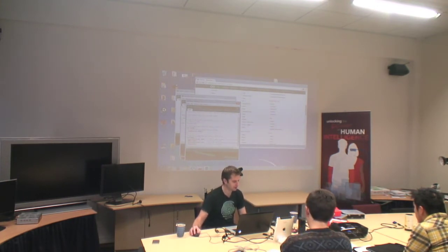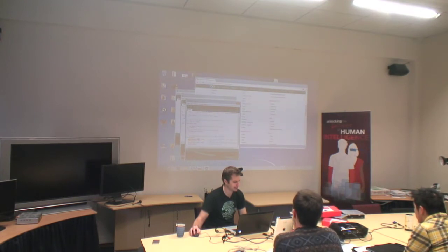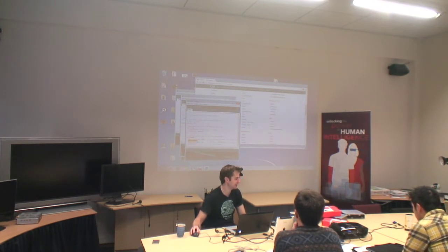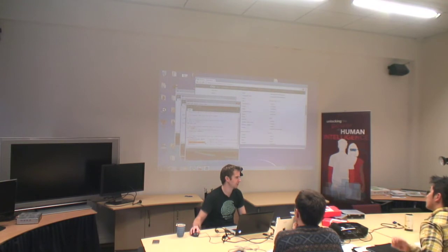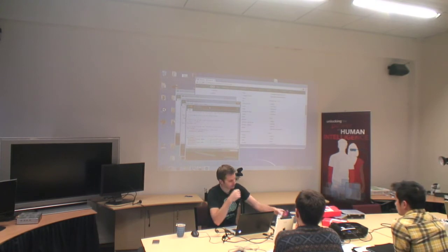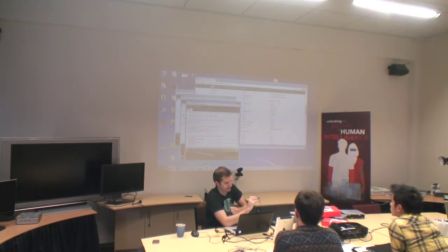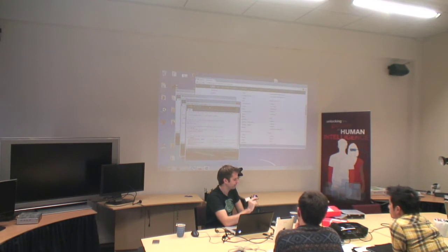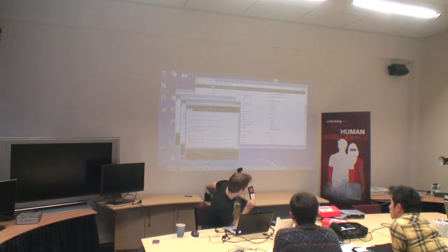And then in our loop function, we write to LED, so pin 13, high, which is 5 volts. We don't actually specify what voltage we're writing with these digital writes. We just say high, which is 5, or low, which is 0. So we write high first, and then we delay 1000, which is milliseconds, so that's wait 1 second. And then we write low, so we set it to 0 volts, and then we wait 1 second. So now if we upload this, it'll compile our sketch and then upload it to the board. And now you can see pin 13 will turn on for a second and then off for a second. Super exciting.